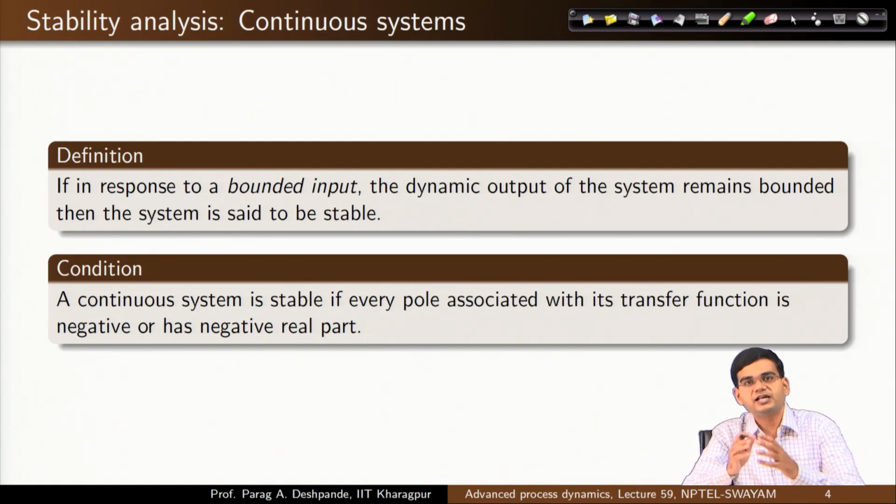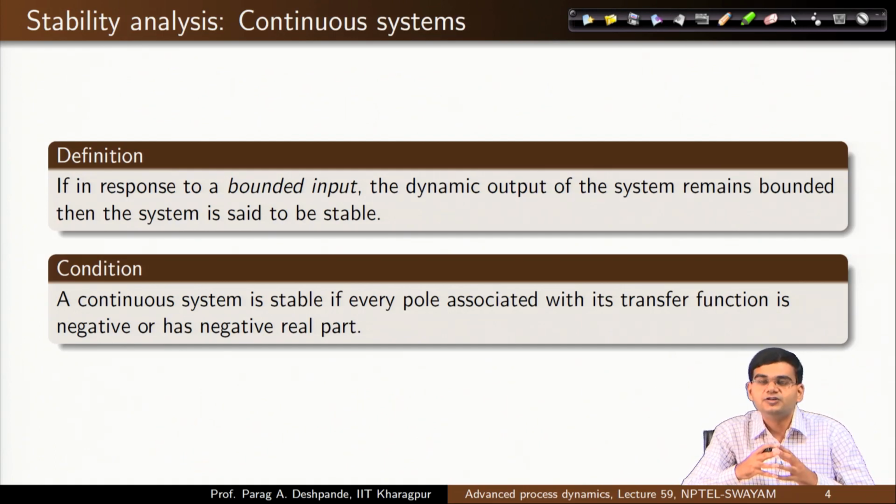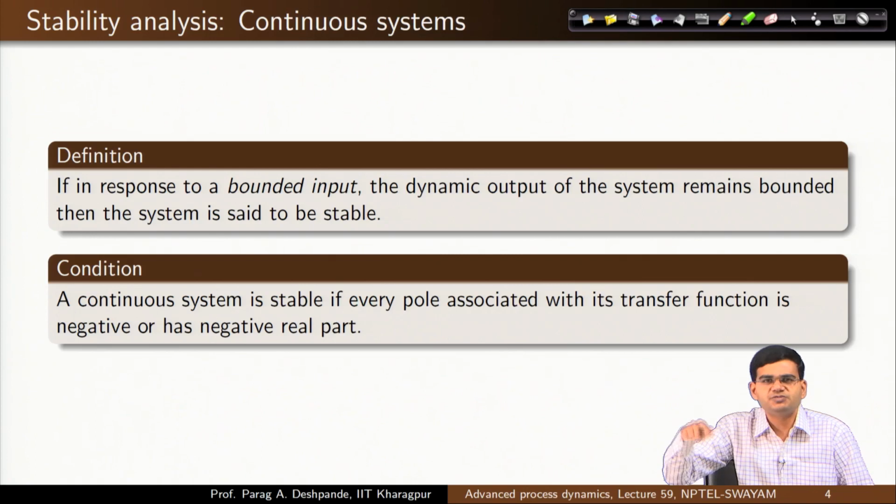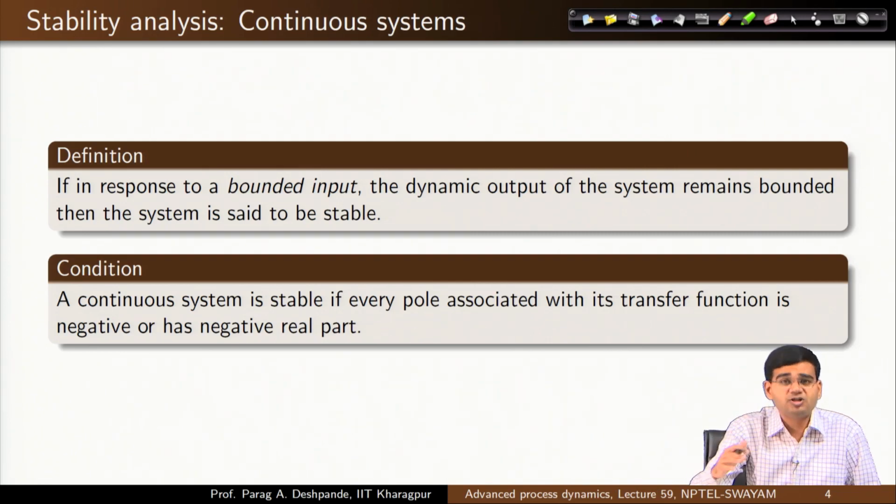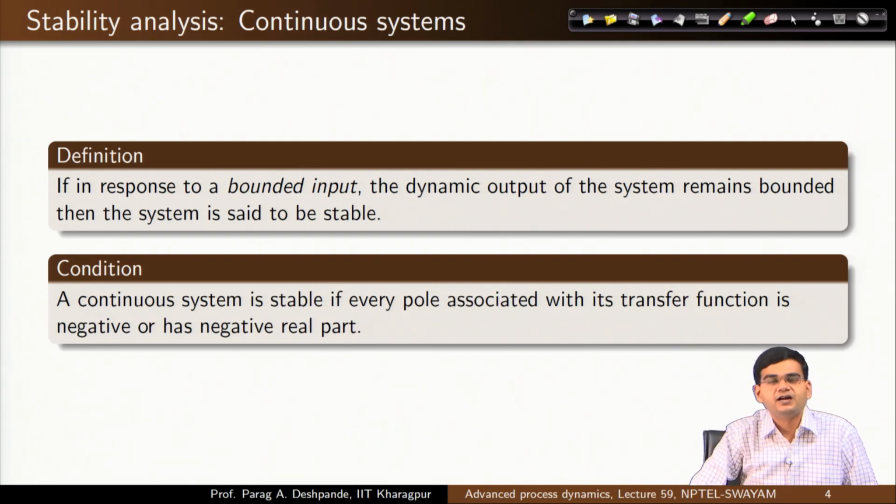When I saw all the eigenvalues to be negative, I used to say that the system is going to be stable. When the eigenvalues were complex numbers with all negative real parts, I knew that the system will have oscillations, but the oscillations will eventually die out, and when they had positive real parts, there would be oscillations increasing in amplitude with time. The oscillations would sustain if you had a purely imaginary eigenvalue.